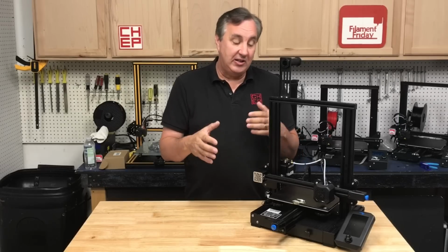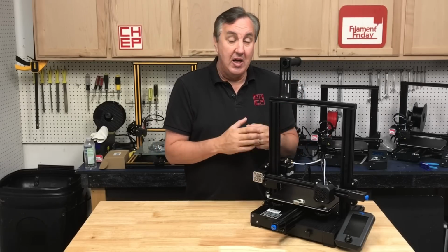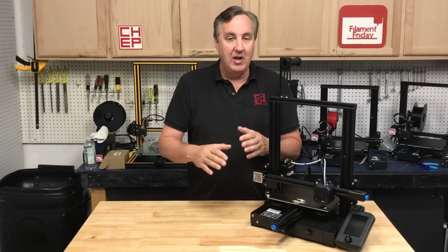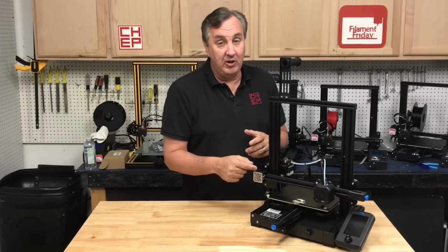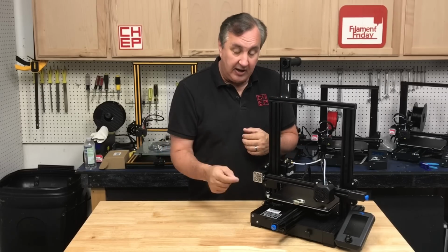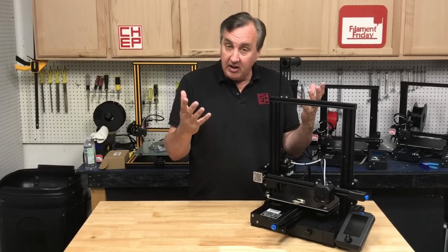In a previous video, I did talk about updating the firmware on the V2, and I made a mistake. I said you needed to rename it firmware.bin. You don't have to. As long as it's a different name than the firmware that's on there, you're good to go. So just put that .bin file on the SD card, insert it, turn it on, and it updates.